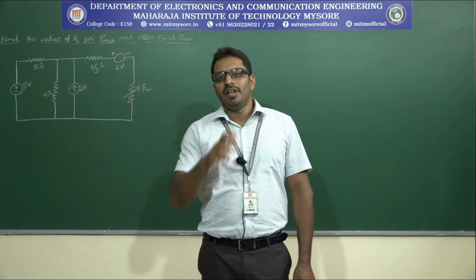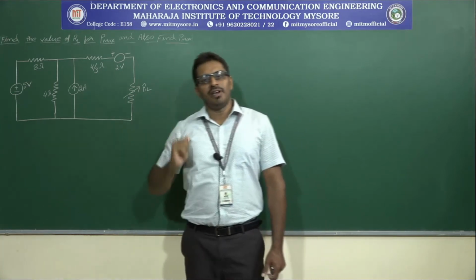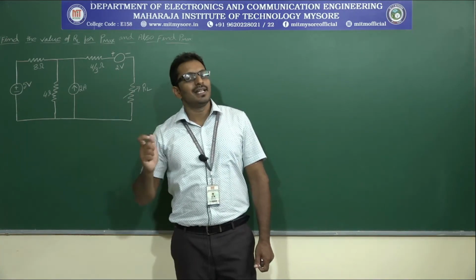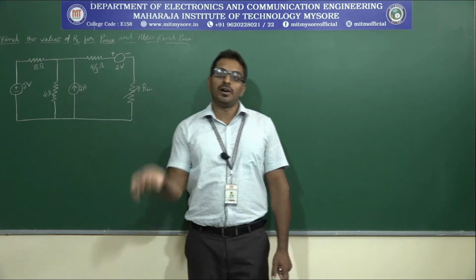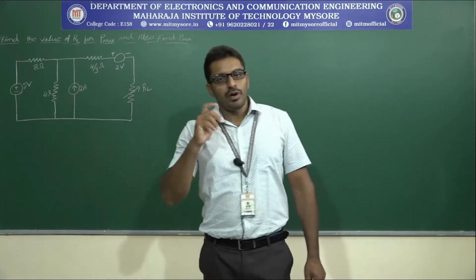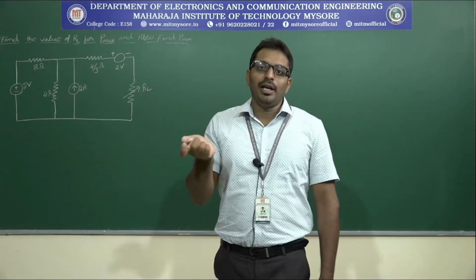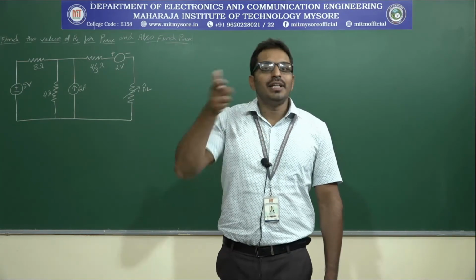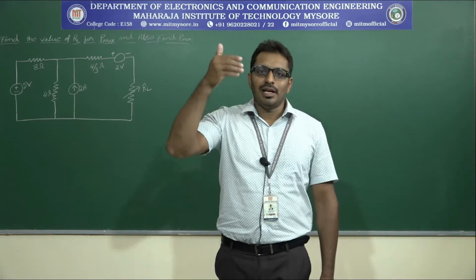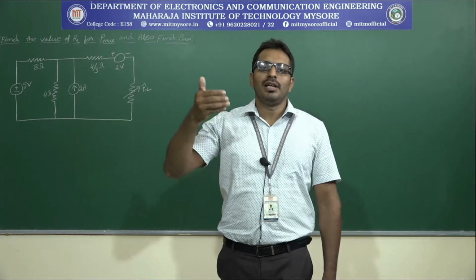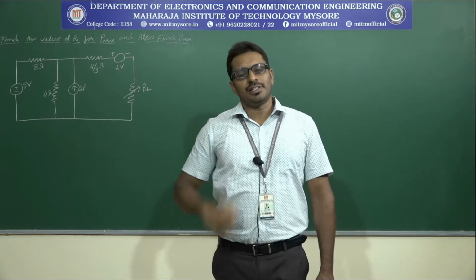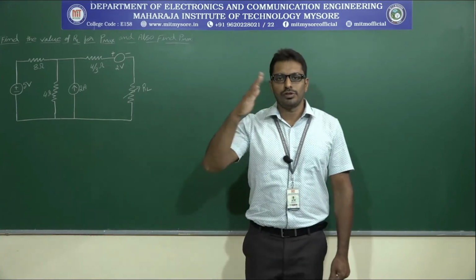In the last case, when an AC source is connected across a variable load impedance, ZL is equal to the complex conjugate of Z0. So only by knowing the type of source and type of load can we determine the condition in which we can transfer maximum power from source to load.